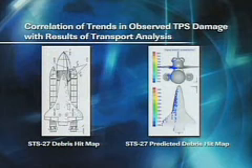And on the left you see on STS-114 a debris map. This was on the orbiter, the regions of the tile that showed impacts, what the little black dots are, after we had a loss of cork off of the solid rocket booster. And what you see on the right, although it's a mirror image, is the simulated distribution. And there's really a pretty good correlation between where the model says the debris should have gone and where we should have had impact, and where we actually observed the impact conditions on the vehicle post-landing.